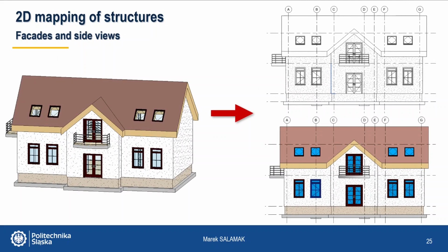An elevation is a perpendicular view of a three-dimensional object from the horizontal plane next to the object. In other words, the facade is the view that the observer looking at the structure from the front, back, left, or right has. An elevation is a common method of representing the external appearance and a detailed description of a three-dimensional object in two dimensions.